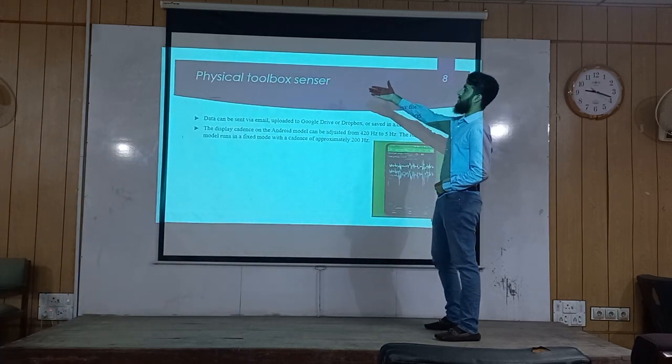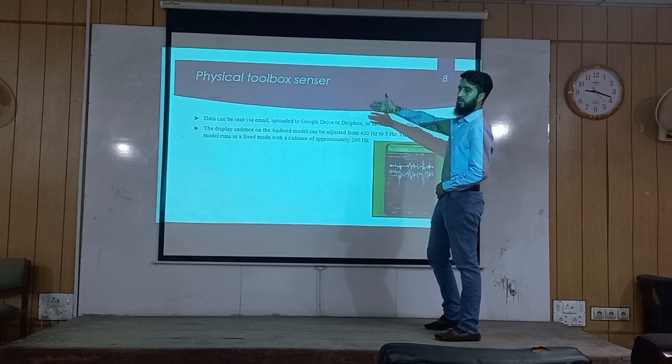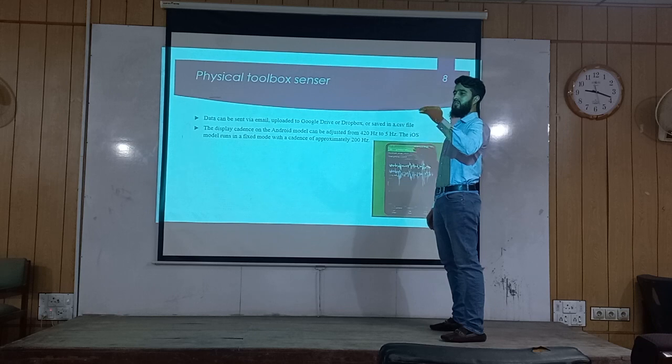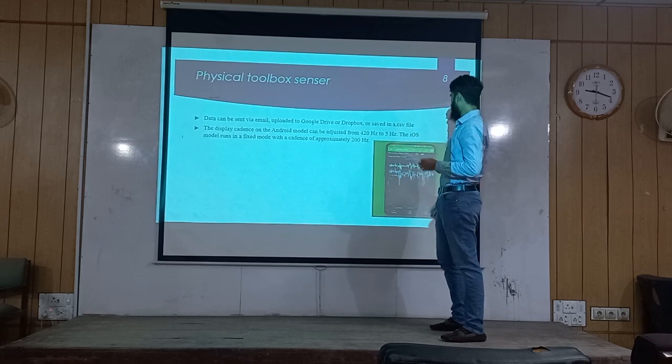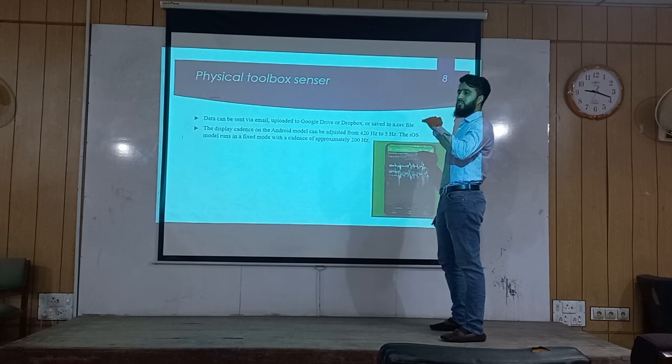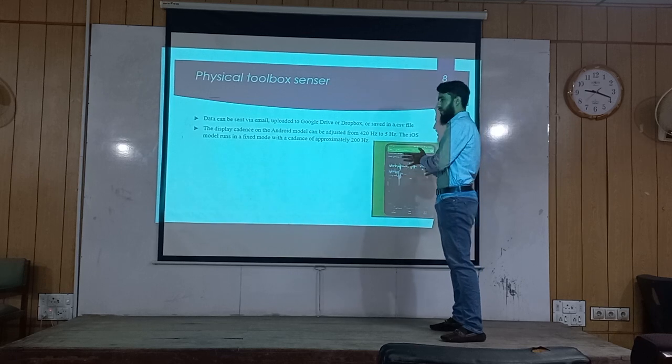So this is our physical toolbox sensor, with which we collected data from bridges. When the truck entered the bridge, we started the physical toolbox sensor, and while it excites the bridge and until it left the bridge, we keep recording. Then we stop and collect the data.